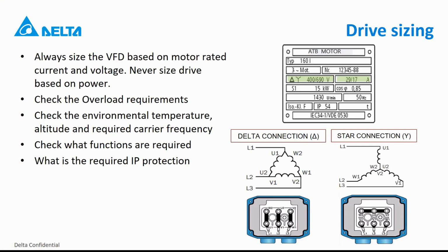In most cases, you install drives in some electrical cabinet, and in those cases, IP20 is okay. But some installations will install the drives very close to the motor, and in those cases, you need around IP55, and you can use the CFP 2000 drive.